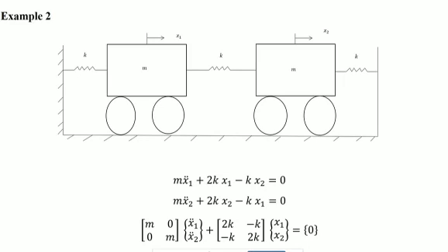So you have to express the n minus 1 variables in terms of the remaining variable. And that's how you will get the coefficient of the remaining variable, and those coefficients will define the shape, while the remaining variable will have the coefficient 1. So that way you will get a vector if you just collect all of them, and that will be the mode shape vector, or mathematically speaking, that will be the eigenvector.